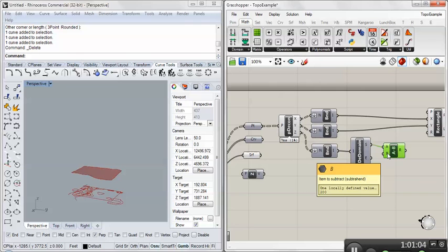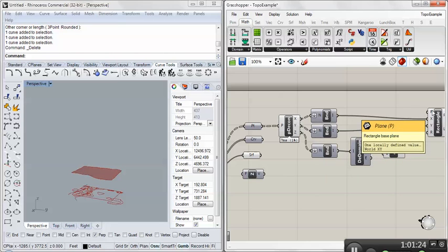And I set the data to 200. So now I'm going to set the bottom of that loft, the bottom of my surface, at 200 feet below the minimum. My value was 925, now I'm at 725. So I can't just drag this value to the point. It needs an actual XYZ coordinate.